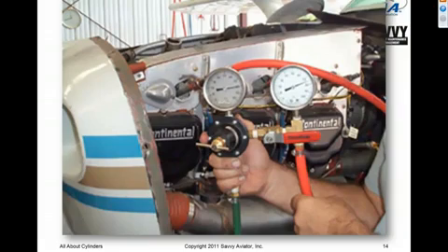I'm sure all of you have seen a compression test done, or many of you have even done it yourself. Basically, we remove the top spark plug from the cylinder, position it at top dead center, and into the top spark plug hole we screw a little adapter that allows us to pump air into the cylinder from an air compressor. For what I assume are historical reasons, we pump air into the cylinder at a pressure of 80 psi. There's a regulator there on the left that we can use to adjust that pressure to 80 psi. We then pass that 80 psi air through a small calibrated orifice and then pump it into the cylinder.